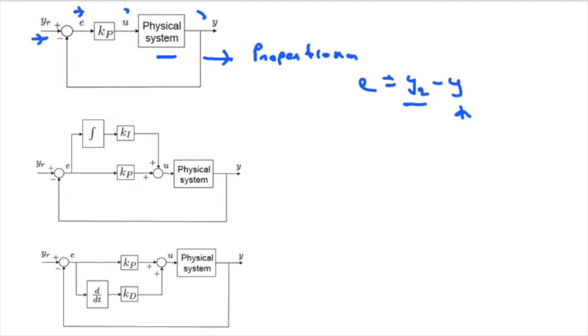Okay. So now the simplest controller is to multiply this error with some gain kp and plug it in as an input to the system. So that if there is an error, the u coming out of this, so now our u equals kp times e. So that's your proportional controller basically. Okay, that's proportional control in simple terms. So you are applying control effort proportional to the error so that the error can go to zero.